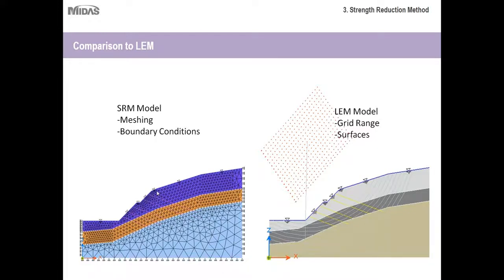The reason this is done is because the smaller your elements are, the more refined or detailed your analysis is. So naturally, you'd want the analysis to be more detailed around the areas where you'd expect more deformation or more strain. As you go closer to where that strain or deformation occurs, the elements get smaller. Whereas if you go to the edges over here, you're not going to experience much deformation or strain at all, so the elements can be much bigger. So that was what was meant in my previous slide about higher order elements. Higher order elements is just another way of saying smaller elements, to get more detailed analysis results.